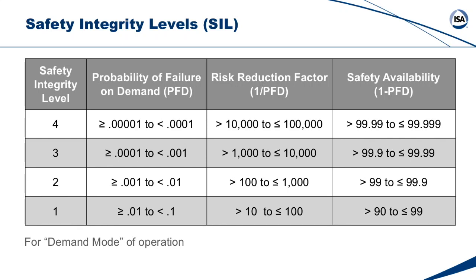Now, it's worth mentioning the earlier version of the standard, or the original 1996 version, only went up to SIL 3. And there was a book from the American Institute of Chemical Engineers, from the Center for Chemical Process Safety, that also addressed these topics back in '93. And that book only went up to SIL 3. We knew there was SIL 4 in the higher level IEC standard. We all stated and thought, well, that's aerospace, that's nuclear, that's transportation. God forbid that's not the process industry. We just don't design things like that.